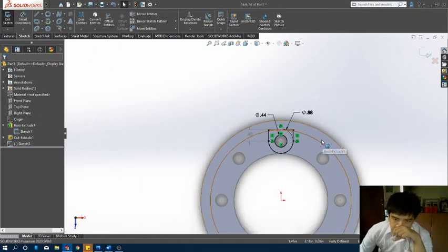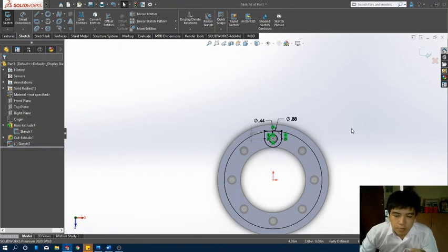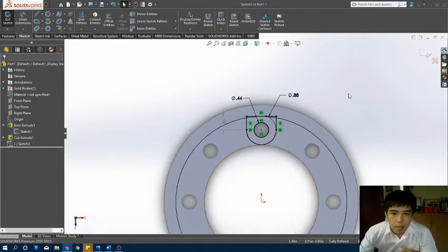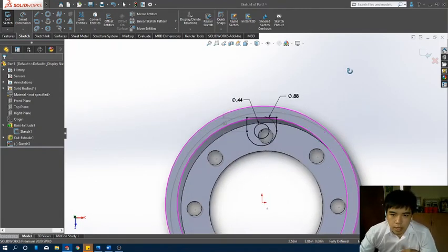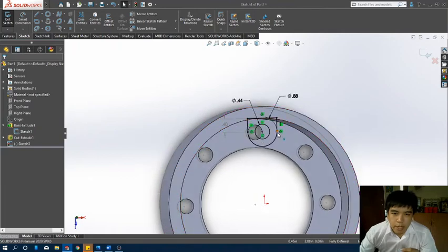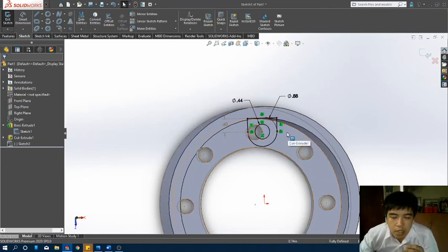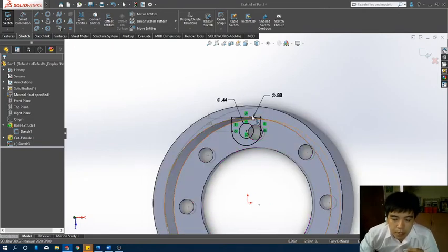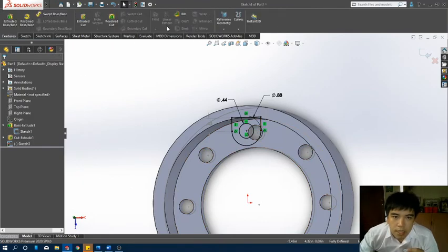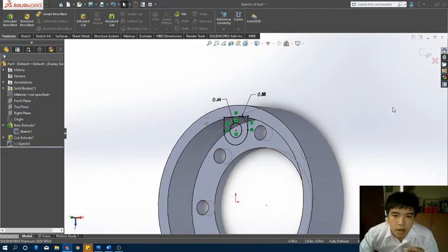So once that's done, what we're going to do is two things, right? You could either extrude this, and from that extruded create a solid body or a solid part, and just recreate that by selecting circular pattern with that object, right?